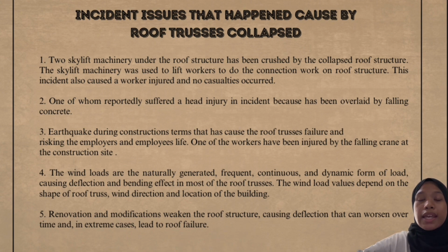The second last one is that wind loads are a naturally generated, frequent, continuous and dynamic form of load, causing deflection and bending effects in most of the trusses. The wind load values depend on the shape of the roof truss, wind direction and location of the building. The last one is that renovation and modification weaken the roof structure, causing deflection that can worsen over time and in extreme cases lead to roof failure.